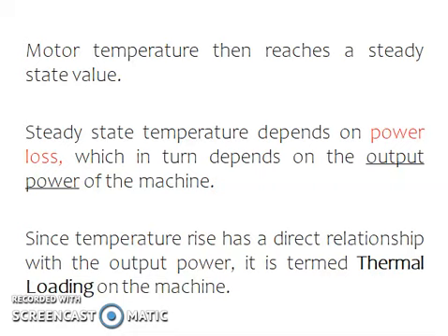This steady state temperature depends on the power loss, which in turn depends on the output power of the machine. Since temperature rise has a direct relationship with the output power, in electrical drives we term it as thermal loading.